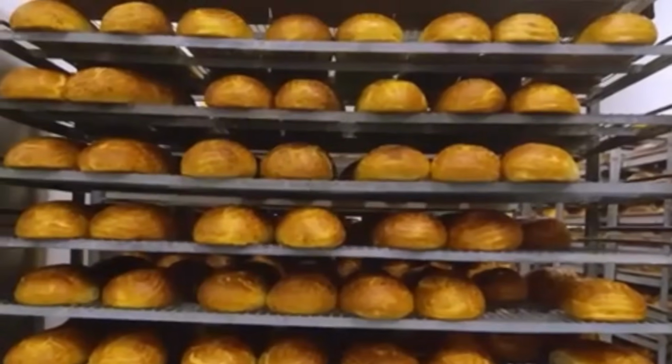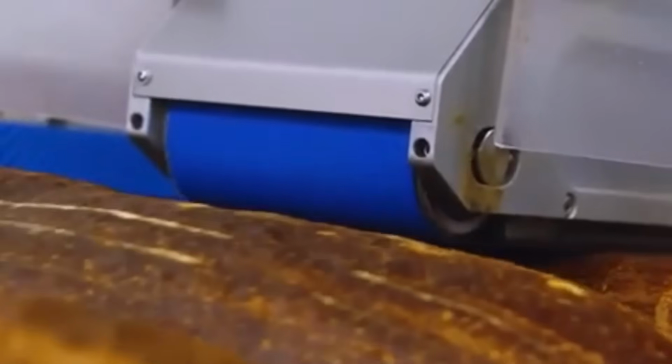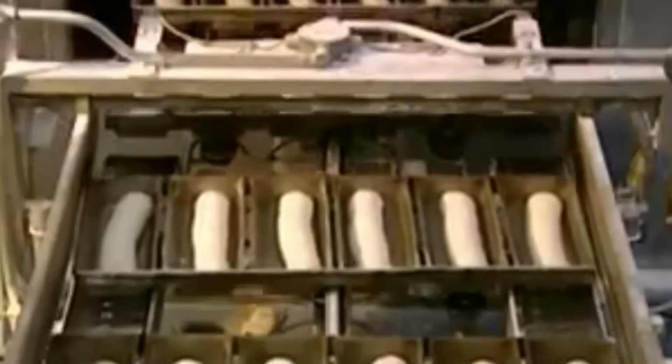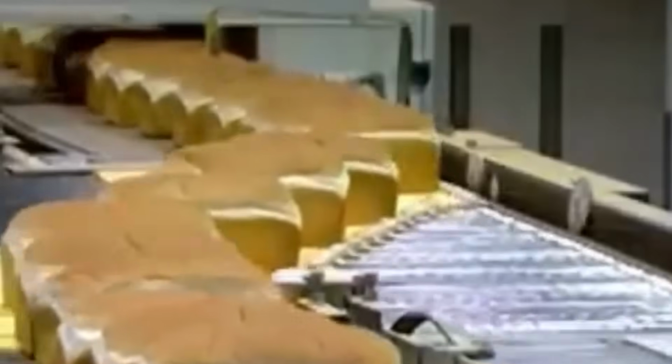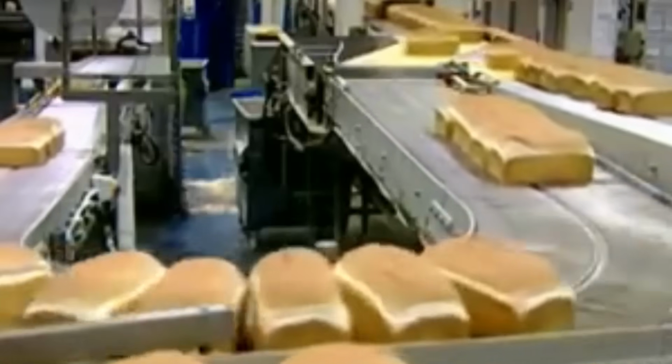Sensors along the proofer track height, spacing, and proofing time. Any variation is logged, and the system will adjust conveyor speed or proofer climate to compensate. If the dough rises too quickly, the texture becomes irregular. Too slowly, and the crust may blister or fail to color evenly. Timing here is crucial. Baking must happen at the peak of fermentation activity to lock in that volume. Once the proofing cycle finishes, the pans emerge from the chamber and feed directly into the oven.